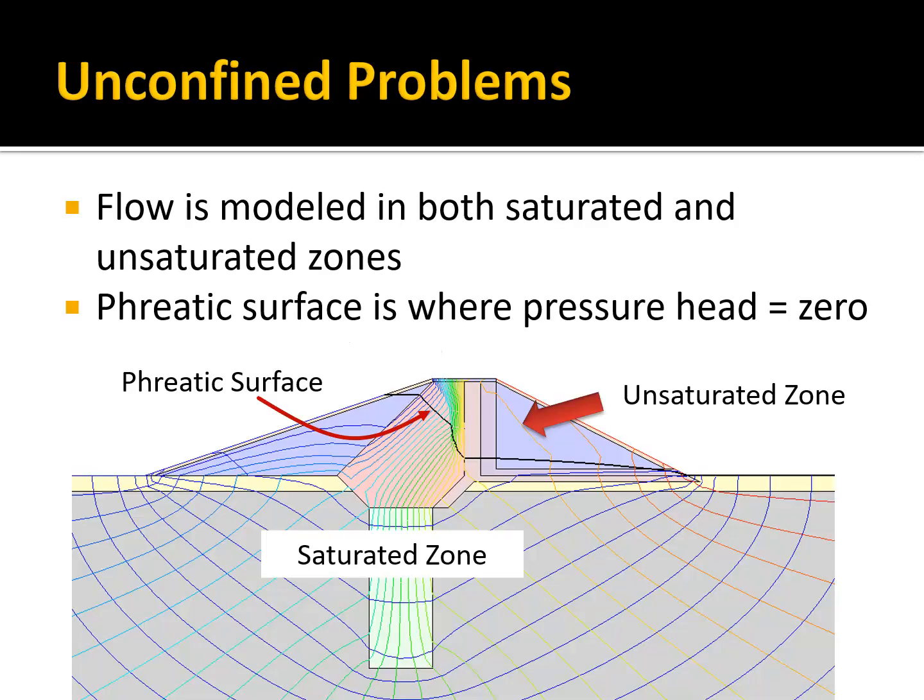Now let me go back to this diagram. So let's look at it. Imagine a vertical slice here in this blue zone. If we're below the water table, Kr equals 1. If you're above the water table, the phreatic surface, Kr is 1 at this line, and as you go up, it decreases down to a minimum value, up to some h min value up here. And once you get above that point, it's the minimum value from there up.